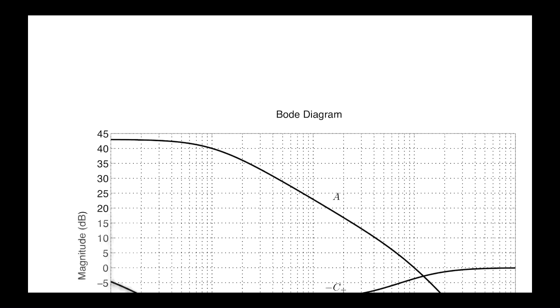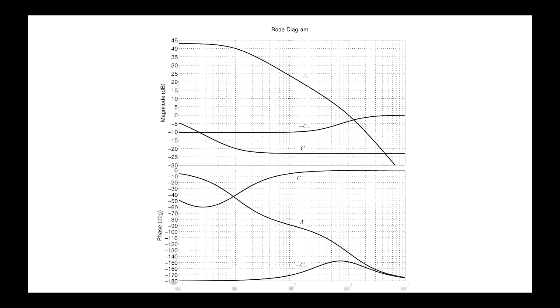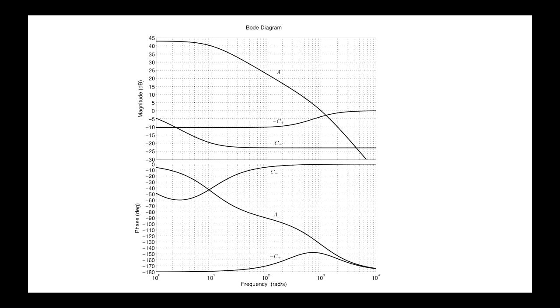All right. So this is what the Bode plots look like. I think the only trick here is that in order to get everything onto the same plot, I've drawn minus the lead compensator. Otherwise, I would have had to draw the phase bit up here. So by multiplying the phase of the phase lead compensator down here by -1, it shifts it down by 180 degrees of phase, because that's what the phase of -1 is.